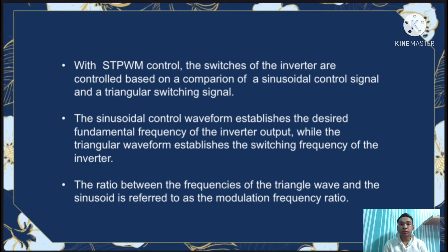The sinusoidal control waveform establishes the desired fundamental frequency of the inverter output, while the triangular waveform establishes the switching frequency of the inverter. The ratio between the frequencies of the triangle wave and the sinusoid is referred to as the modulation frequency ratio.